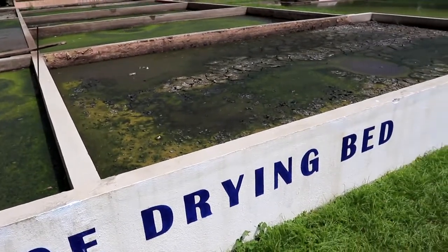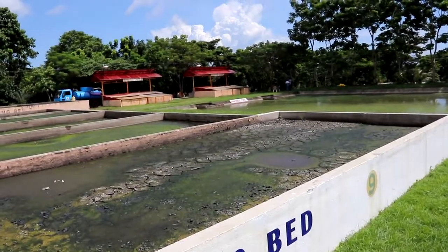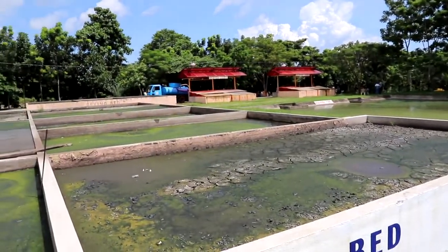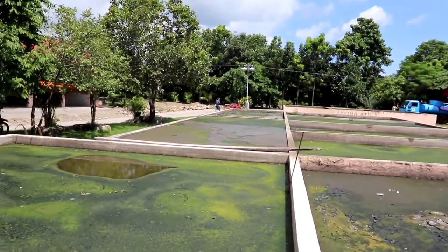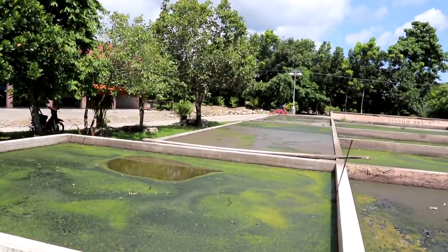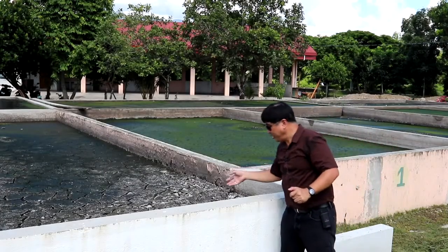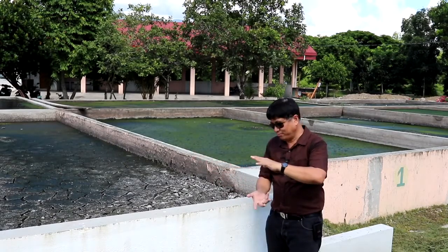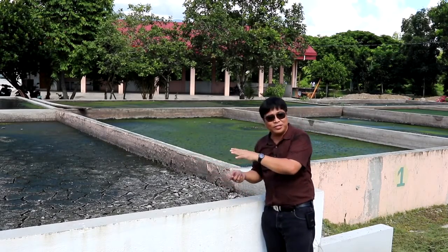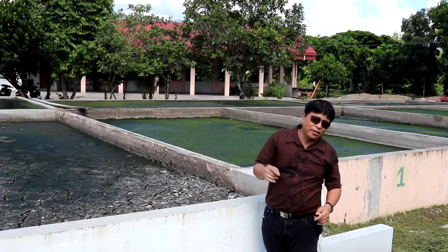Operators should keep track of how long it takes to dry the sludge. This might be an indication of clogging of the sand, which is a problem that can be easily fixed just by scraping the top 2 or 3 centimeters. And you can see, you spread the sludge evenly, roughly from 8 inches to 12 inches at the most. So you let it stay there for